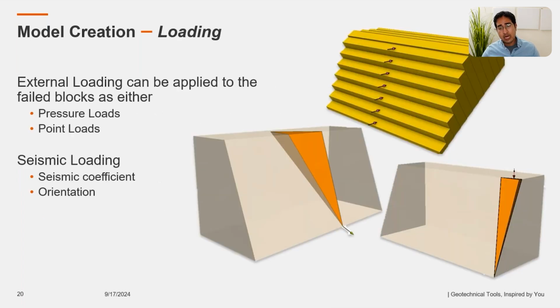occur. Now that we've taken care of the geometrical properties of our slope and blocks, oftentimes users are interested in modeling the influence of external loads. And once more, most of the model inputs in RocSlope2 are defined once, and this is actually propagated to all 3 analyses and to each block's form for each analysis. External loads can be applied to the slope face as either pressure loads or point loads, and users can even define a pseudostatic seismic load using a seismic coefficient.